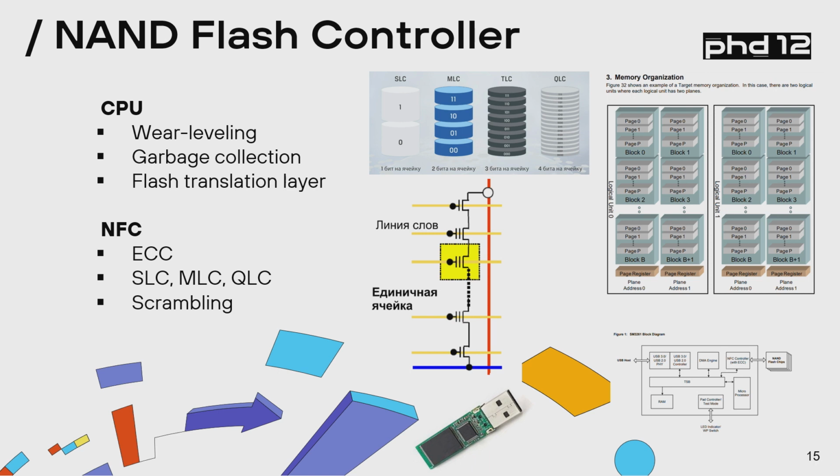So what does the flash controller do? That's the hardware module that doesn't really depend on the programmer. So as a developer, you should be able to set it up easily. Like I said, memory is prone to degradation, so bit errors can easily emerge. Correction codes can obviously help you. So during the reading process, the flash controller can identify errors, and then as a software developer, you will be able to read the right data from NAND directly.